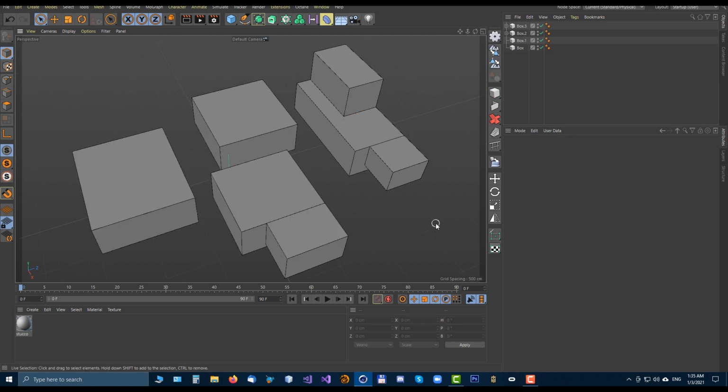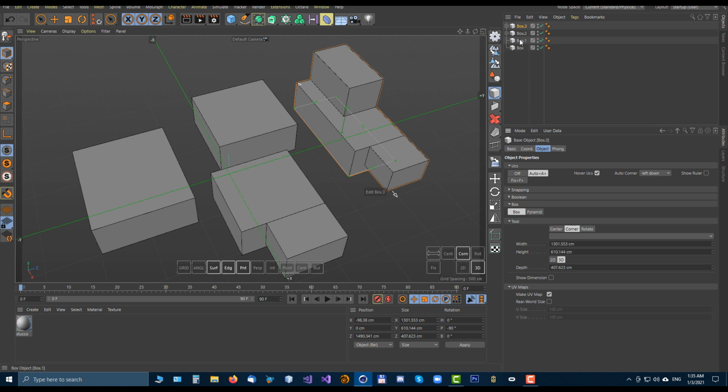If you drop creation of the parametric object completely and you select a created object back, you can switch back to the edit phase of this object by activating edit phase here. And now when you are switching between objects, you are still in the edit phase of the actual object. So as long as you keep the parametric objects not converted into mesh or polygons, you can still adjust all parameters.